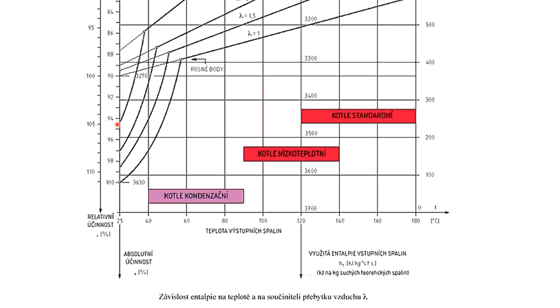And the Stirling engine system would most likely have the oxygen excess a little bit higher than 1, but maybe not that much. So let's say that it would have oxygen excess of somewhere between 1 and 1.5. So it would be a point somewhere over here, where there would be a line in between these two, and that would mean that the flue gas at the outlet of the system needs to have a temperature of about 45 degrees C. That's already quite cold, and we still need some minimum temperature difference to be able to transfer the heat from the flue gas into the heating water.